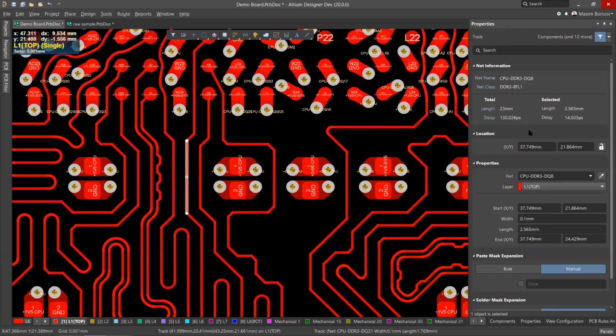For example, you don't need to calculate the propagation velocity factor, because it's built into Altium. The only values required are the length of the trace and the actual geometry. It will recognize whether that is a single-ended trace or a differential pair.